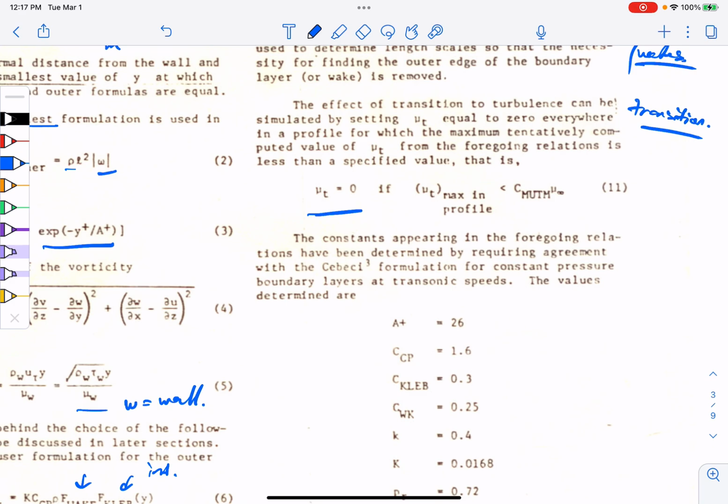And as the flow progresses, if you have shear, like partial u, partial y, then the eddy viscosity should be increasing. But even if you have a tiny little bit of eddy viscosity, it might still be seen as a laminar flow, because it has very little effect. And so he actually has a small value of eddy viscosity where he would trip the flow and trigger it. Alternatively, that's a way to try and predict transition without setting it empirically in advance.